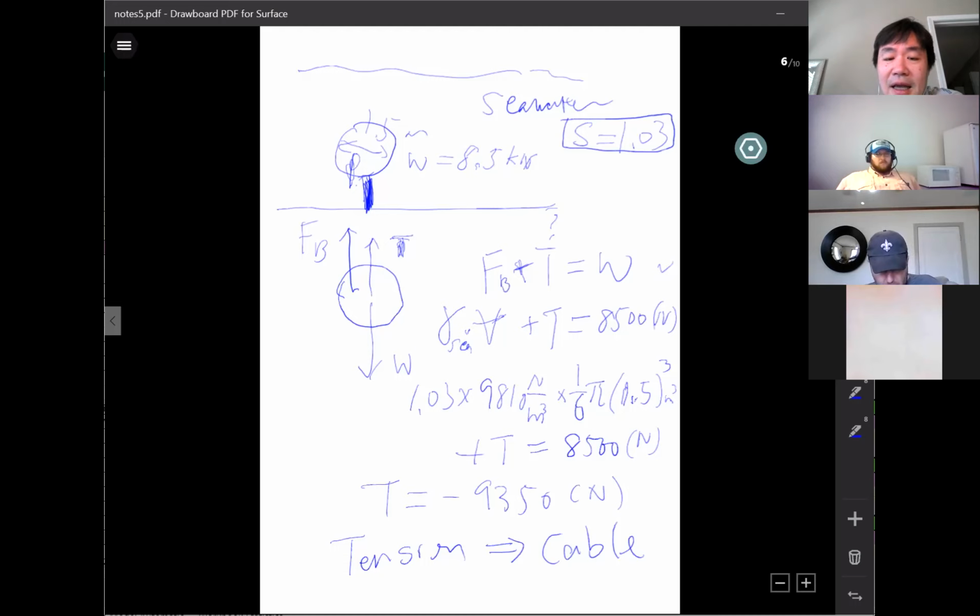The thing I want to emphasize here is for those unknown direction forces on a free body diagram, don't be afraid. Oh, there's that force, I don't know the direction, how do I draw it? I'm very comfortable with putting an arbitrary direction if I don't know the force direction. I like things I don't know. I just put an arbitrary direction, then let the calculation eventually tell me the direction of that force.